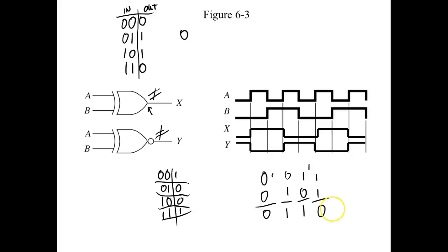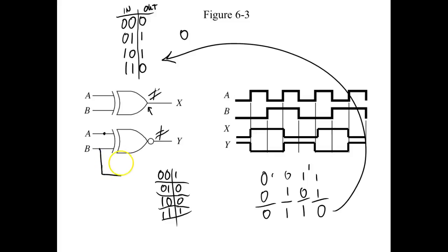Okay, y'all, and that's the truth table for that gate right there. All we've got to do is take care of the carry, right? You understand that? So if I take care of the carry by coming up here and putting an AND gate, that would be our 0 with a carry of 1, right?